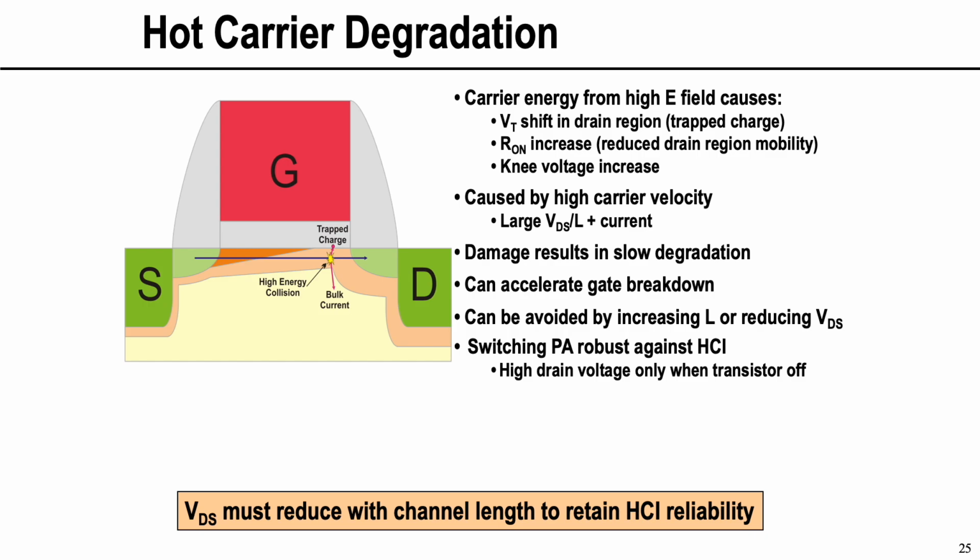Now, one of the breakdown mechanisms is basically, if you think about this gate oxide, by the way, the other way to make the transistors good and fast is to make this really, really thin. This is several atomic levels thick, maybe like 3 atoms or 3 layers of silicon atoms thick, right?